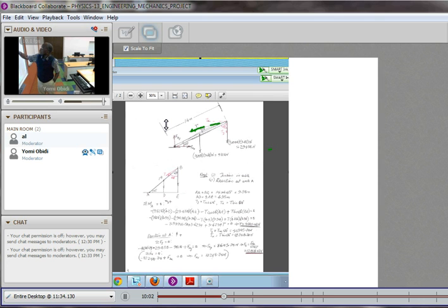When we break that T into its X and Y components, we have T sub X right there, and we have T sub Y. So that force has been dissipated into its two components, to say two-dimensional representation. And we're already given that the tension, the cable is acting at an angle of 15 degrees from the boom. So we have that.